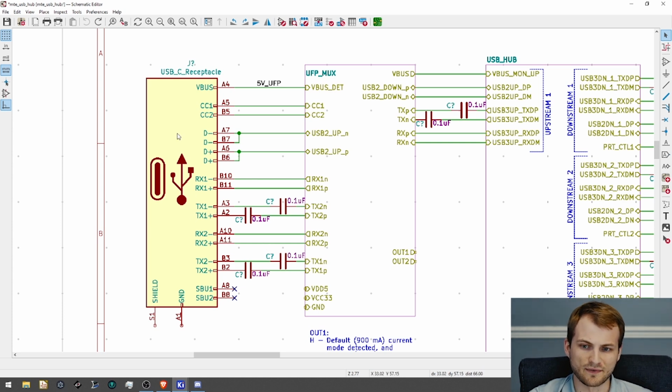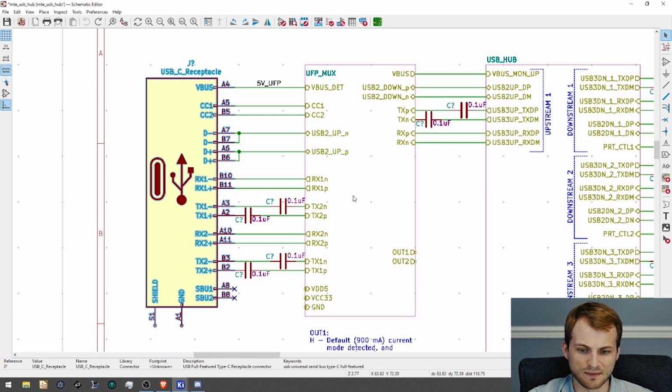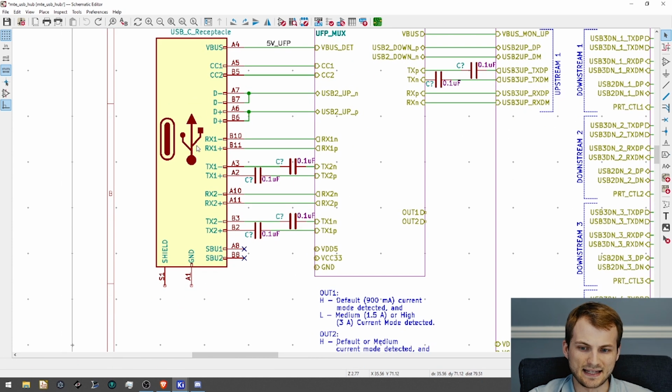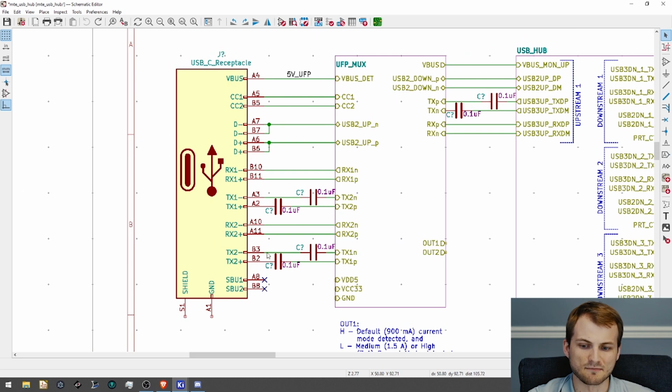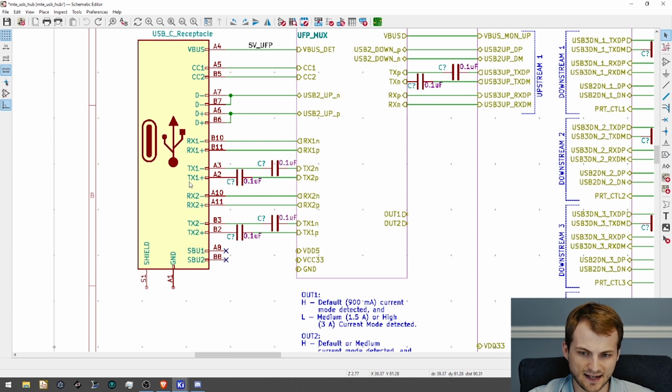It also helps if you happen to have a common mode voltage here that is a lot different from your common mode voltage here. The differential pairs tend to be more sensitive to that because you can't have as much protection from Zeners or TVSs like you can on the slower speeds. So the caps protect them, because it doesn't matter what the voltage is on the DC side, it's not going to get passed through.